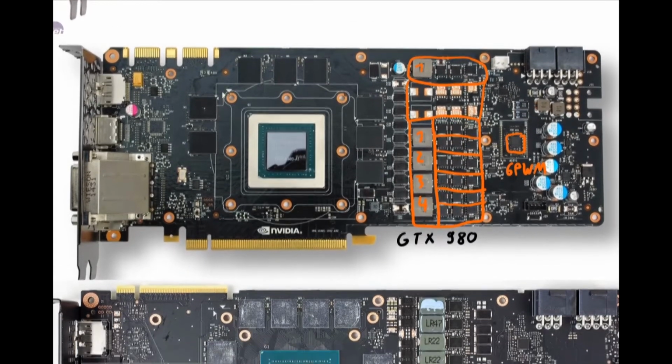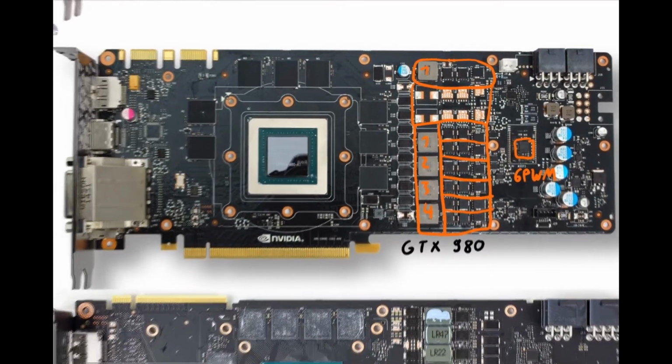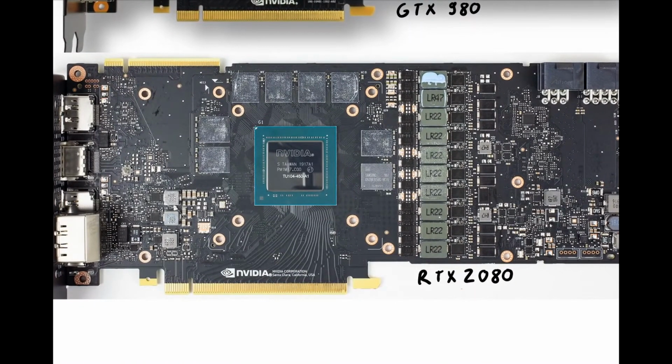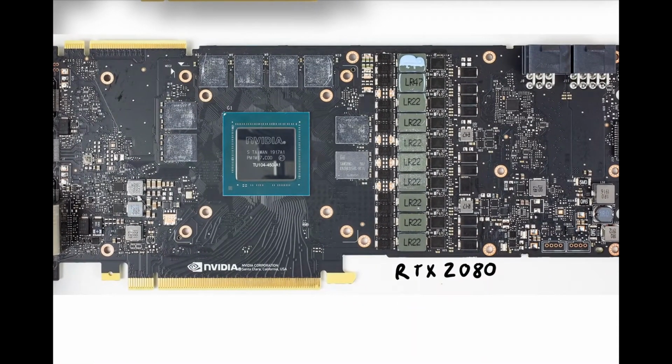And yeah, you will see it on cheaper cards, and up to the GTX 980 Ti, Nvidia's reference PCBs were pretty cheap. This is post 1080 Ti, so this is a very much better PCB than the previous Nvidia reference PCBs. So here we see for the first time that power stages are used. And power stages compared to discrete MOSFETs are very efficient, and they can handle a lot of current. But the thing is, like they integrate several things.